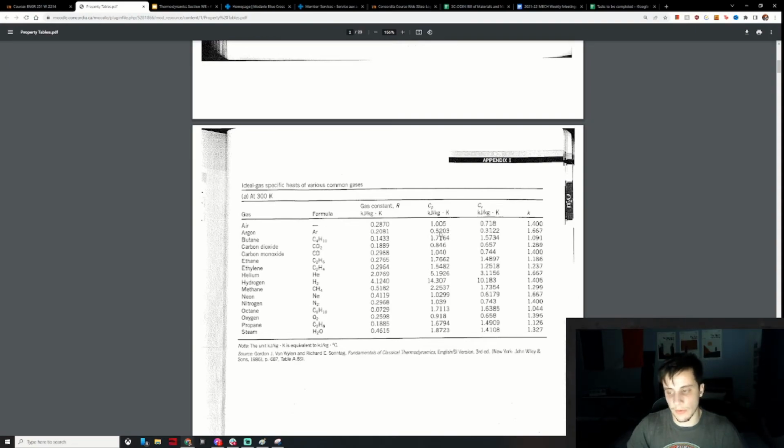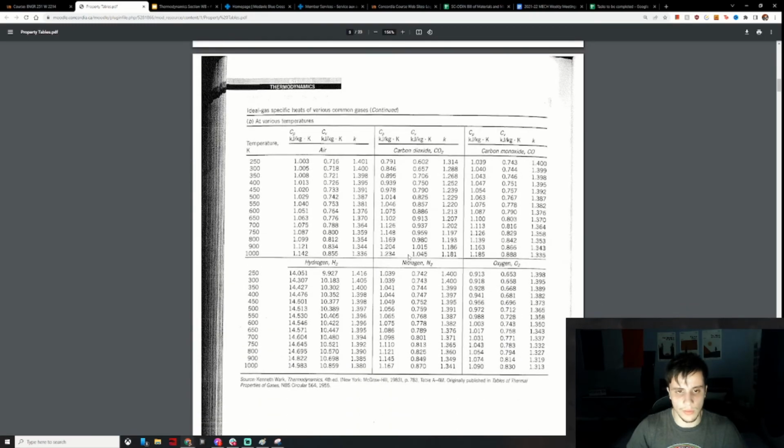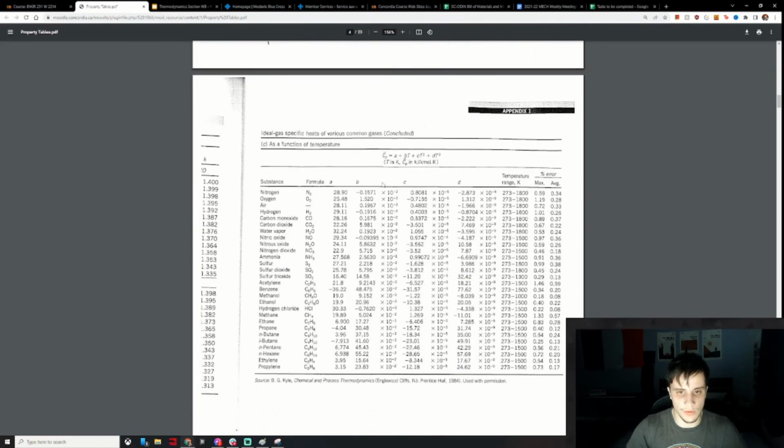That's what they did with the correction. Technically, it's wrong. This is the specific heat for constant pressure at 300 Kelvin, but we're at 723 Kelvin, so it's wrong. But just take this one in this case, since I don't think it changes that much. Or worst case scenario, you use... oh wait, no, you can't. We didn't find it.